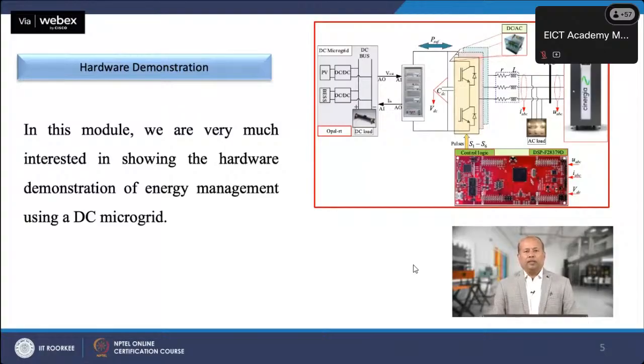Here, the AC load is a bulb load, and the IGBT stack acts as an interface between the AC grid and the DC bus, which is called an interfacing converter. The control system of the IGBT stack is implemented in the DSP controller.